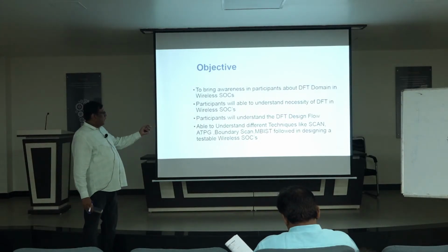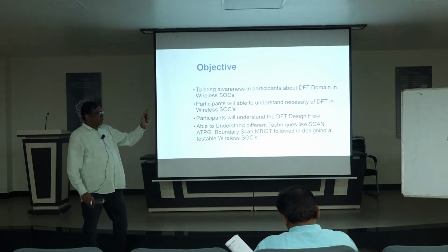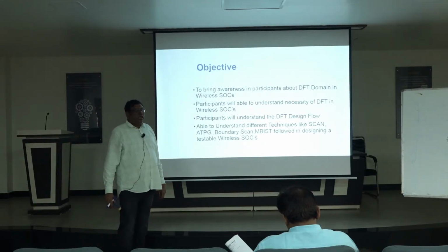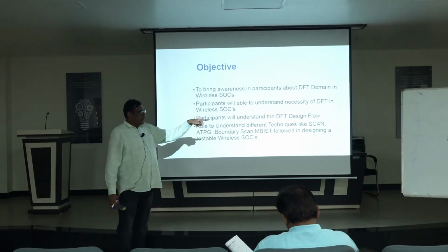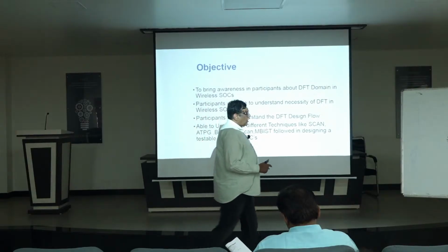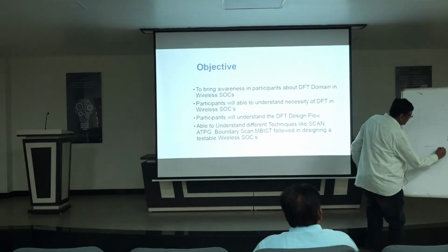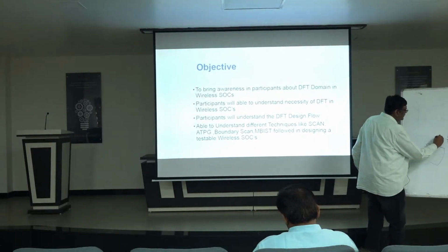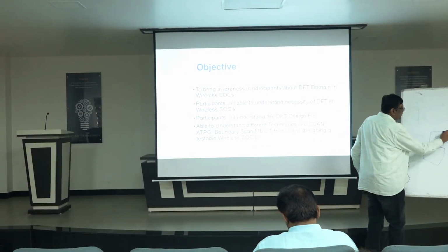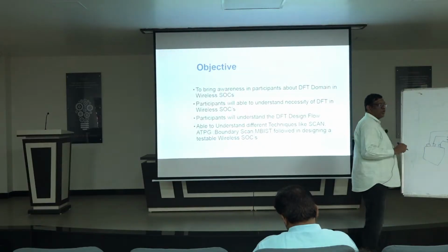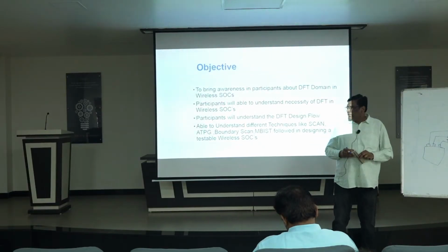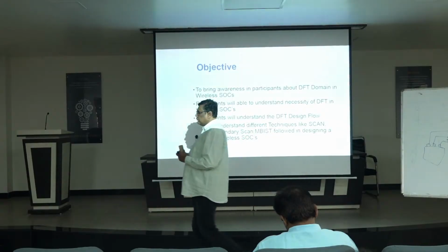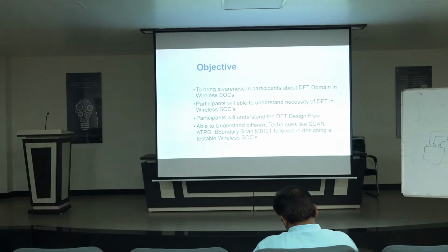Scan and ATPG are related to the glue logic, RTL, and boundary scan is related to all the IO pins. On a PCB there are so many ICs. How to check the interconnections between IC and IC will be done by boundary scan. So all these techniques we will try to understand.